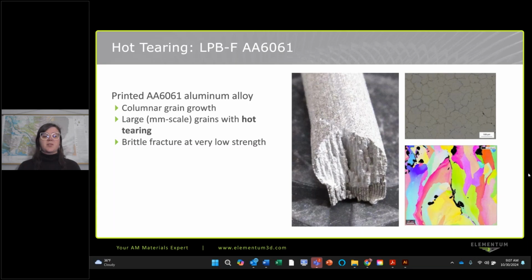Basically in between those grains, we tend to have hot tearing or solidification cracking occur, and so we can't really use this material as is off the shelf. And so while these materials are great, we want to use them, this hurts the supply chain that we can't just use these off the shelf. And so we started by using our technology for these materials in particular to develop more aluminum materials that are printable for AM.